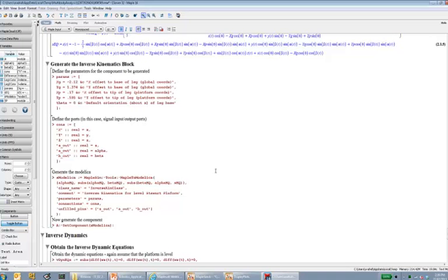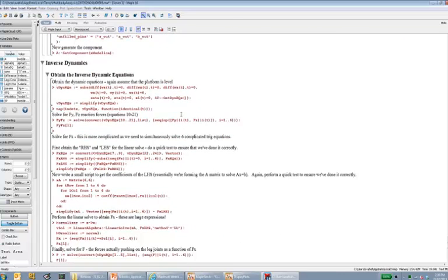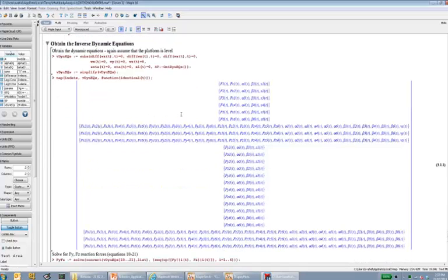So let's continue on what we were doing, and basically continue on the inverse dynamic calculation. For that, we will first need to define the basic relationship. As I mentioned, we will set zeta, eta, and xi to 0, and also the first and second derivatives to 0 for this particular example. Then we look at the constraint equations and see which one includes what variables. The same thing that we did with the constraint equations, we can do here.